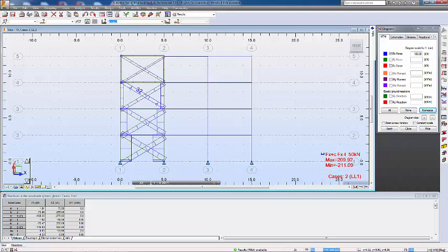So the two systems work together and can withstand the loading quite efficiently. You possibly see in some concrete buildings they're not using the diagonal to build this. Instead, they use a shear wall put in the corner of the building to take the lateral loading. That is a quite efficient system as well. So this is the actual force.